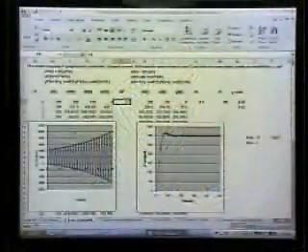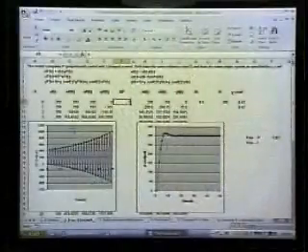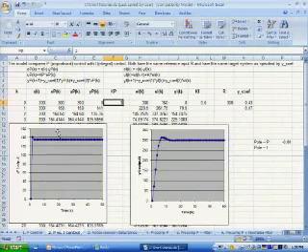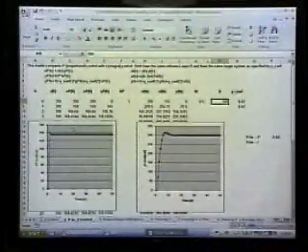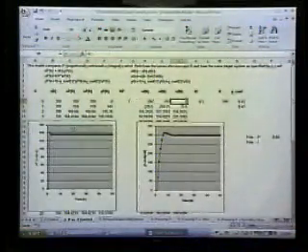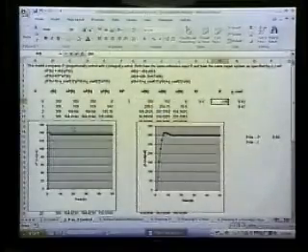Now, we've played with this before, and we saw what happened with the proportional controller. Let's also take a little look at some of these characteristics here. So I think before we found that if we had some slightly smaller values for KP, we could make the system fast. We just have this problem that if this is our reference input, then we're off by quite a bit. I guess before I did 200. Let me switch this back to 200.